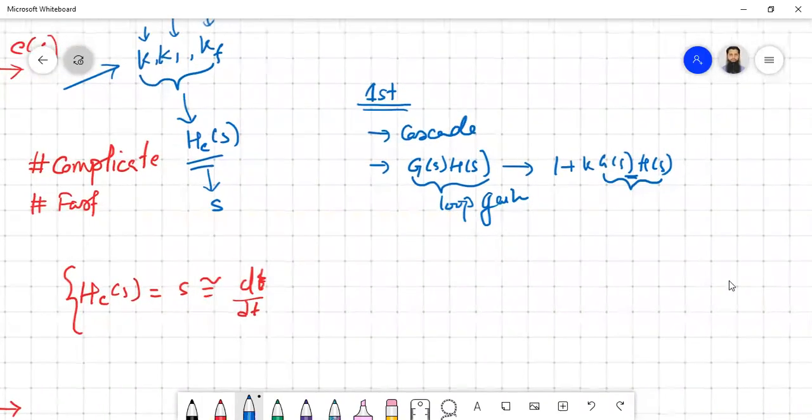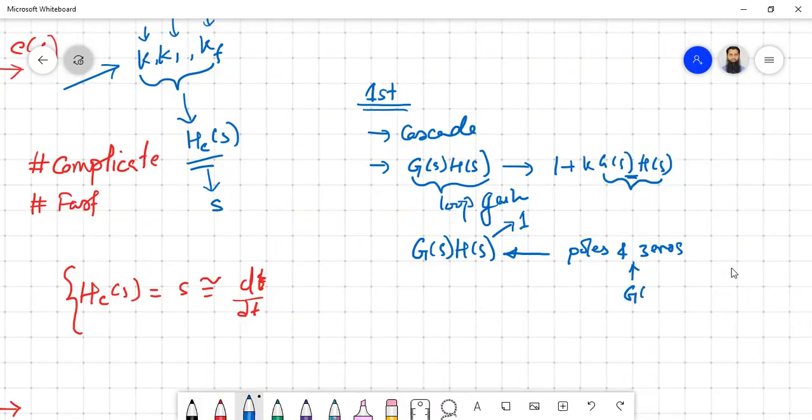In the previous case, in the cascade, what we have done here is we have plotted the root locus based on your G of S, H of S. That is different, as your H of S was 1. Here, to modify the root locus, what we have done, we have added poles and zeros to have our desired performance, zeros in the cascade, or actually we have included in series with G of S. So we have changed G of S, poles of G of S is added, and we actually design our compensation.